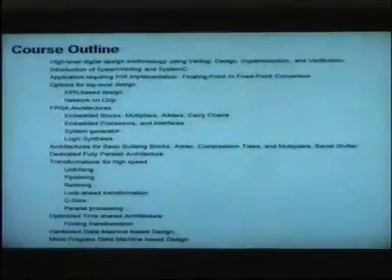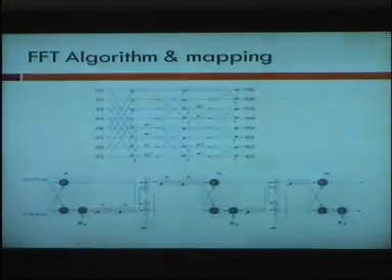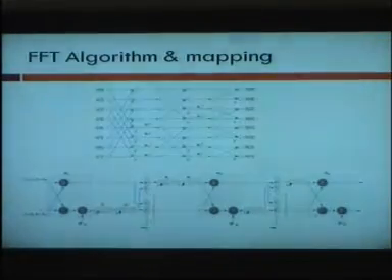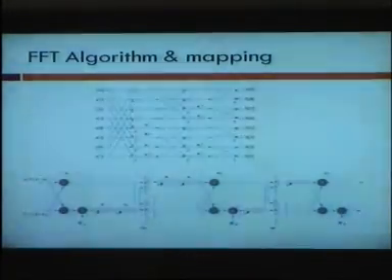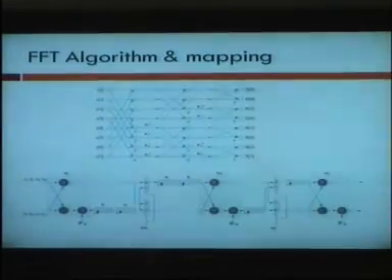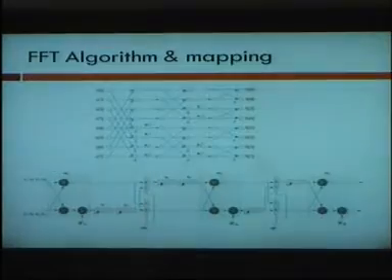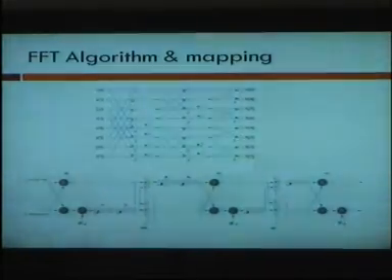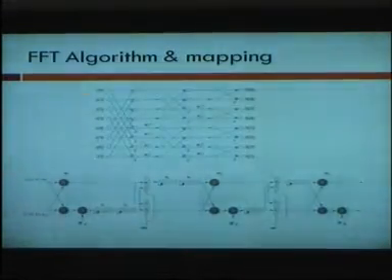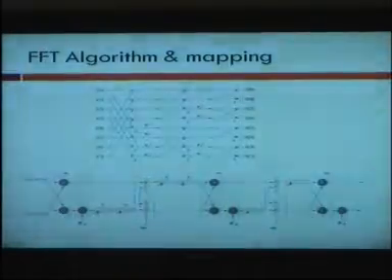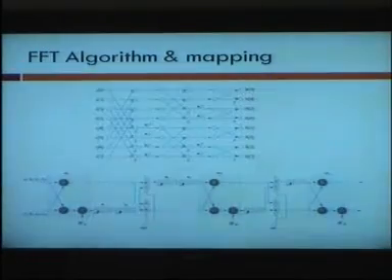Then I'll come to another interesting topic, which is the time shared architecture, where actually you are folding. The folding means that this is a good design where you have folded the design by 4. So by 4 means you are only using 1/4 of these resources. You can fold it by 12 times as well. By 12 times means there will be only one butterfly. So one butterfly, you use it 12 times to do your FFT. You can fold it by 6, by 2, by 3, by 4.